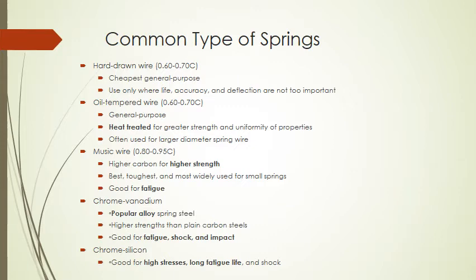For this purpose, different types of material have been suggested and different processes in material science have been carried out, like different types of tempering and other heat treatment processes, to achieve good linear behavior of the spring and a greater life. So these are the challenges in material science: to have a material that has linear properties, a long fatigue life, high tensile strength, and high shear strength. These are the big challenges in material science.